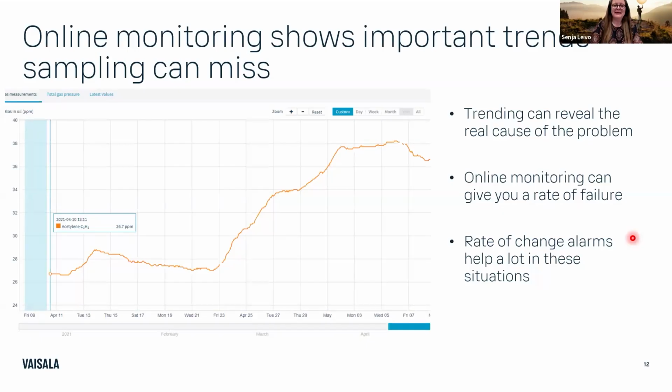And yes, if you have a hydrogen monitor and you are not familiar with stray gassing, definitely people think, okay, is my transformer having PD, and that concerns people. So yes, definitely that is the case.